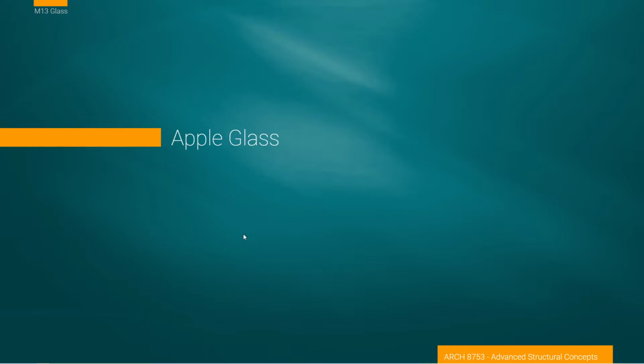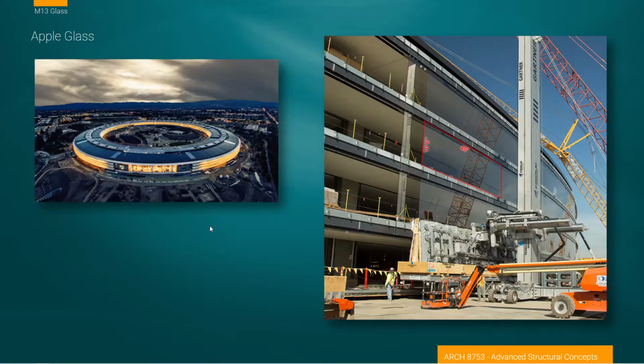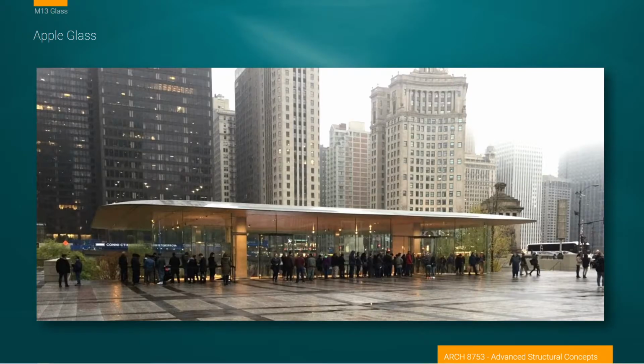One of the leaders really stimulating the industry, both from the architectural standpoint and the product standpoint, is Apple and their utilization of glass. They really pushed vendors to the limits of what they can produce. Steve Jobs, before he died, had envisioned these large glazed panel systems that surround their headquarters building in Cupertino. This is an illustration of the size of those panels, 46 feet long, 10 foot 6 inches tall. These are some of the largest glass panels manufactured, I believe, in the world.